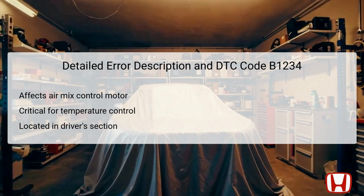DTC B1234 alerts technicians to a short circuit issue specifically within the air mix control motor circuit. The air mix control motor is crucial for managing the air temperature that flows into the cabin, allowing for a comfortable environment based on driver and passenger preferences. Typically located in the dashboard area, this component requires access to the vehicle's interior systems for inspection. A short circuit in this context implies that unintended current flow is occurring along the circuit, which could manifest as insufficient temperature control or a complete malfunction of the heating and air conditioning system.